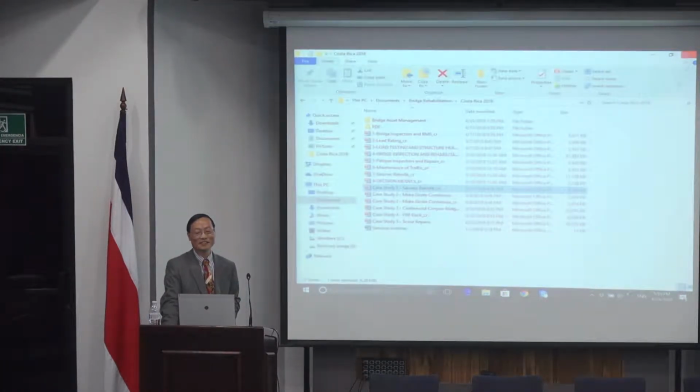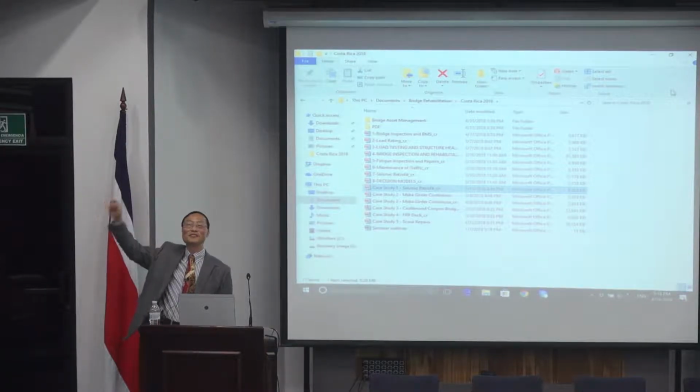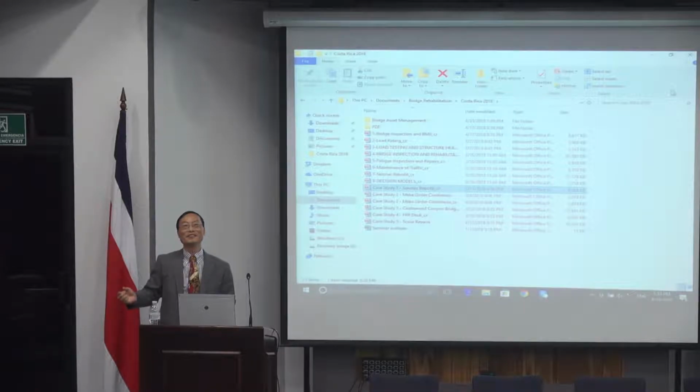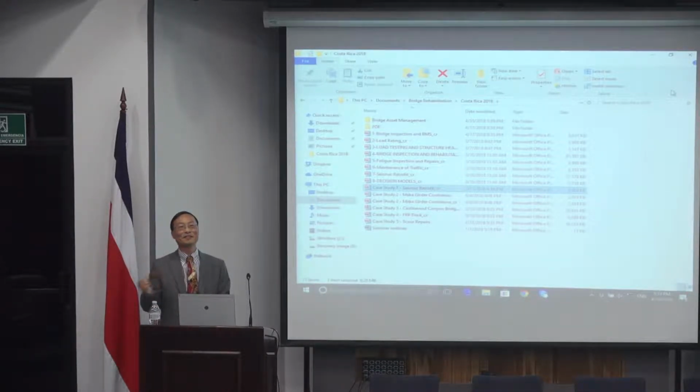Other scenarios, as I said, there will be the three things we discussed earlier. One is to prevent it from falling down. For that one you simply use cable restraints. Another is if the shear column is too weak, you may just enlarge it, or if it's a little bit too weak, you just wrap it with FRP materials. And another is folding, as I said.